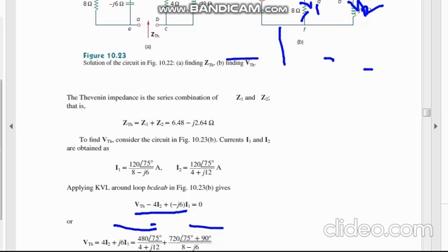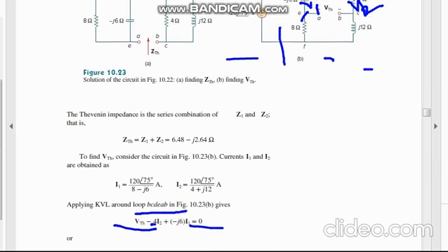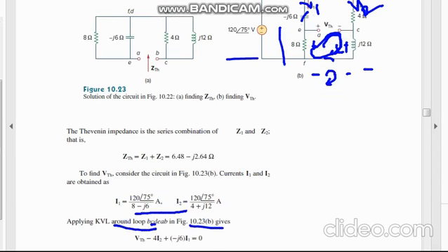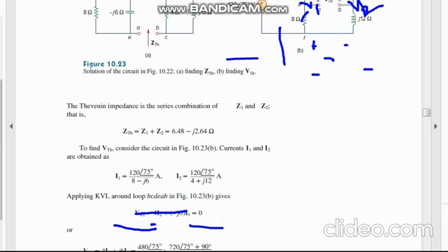It's not only this. The two voltages will be applying KVL around this port. Around this port, you can see V1, V2. This voltage is V1, that is V2, and applying KVL through this, that will be V Thevenin plus V1 plus V2. It's like this, minus plus minus. All the voltages will be in KVL format in this loop here. So you can find out by applying the KVL, Kirchhoff's voltage law.